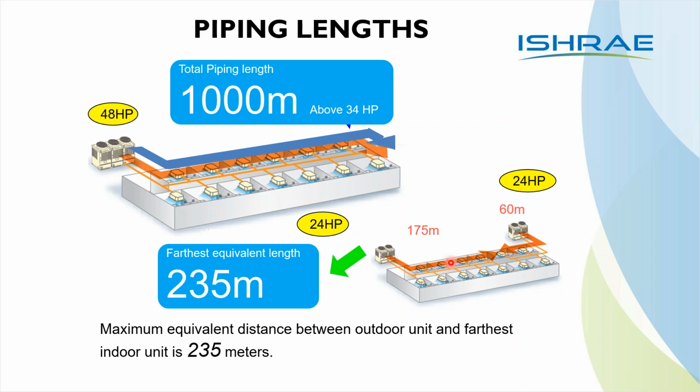What is the quantity of piping which we can do? Now, can you see this? 1000 meters. 1000 meters is 1 kilometer. Does it mean that I am going to keep my indoor unit here, dig a trench for 1 kilometer on the floor and take my pipe for one outdoor unit there? No. Please note, when we talk of piping, it is the total piping length.